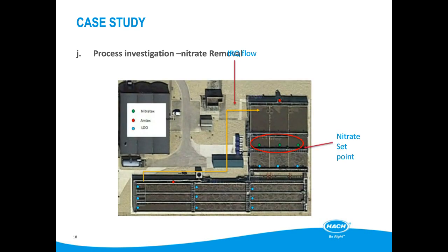This is how that looked on the site. You can just about see the return lines at the start of the anoxic zone. At the end of each, the internal recirculation is taken from near the end of the aerated Zone 4. The end of each anoxic zone had its own nitrate measurement for security, but a single nitrate measurement would have still worked.